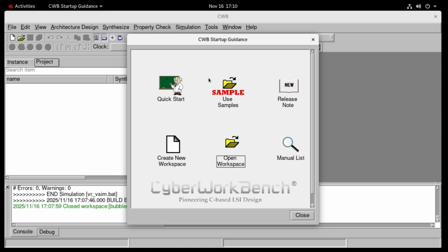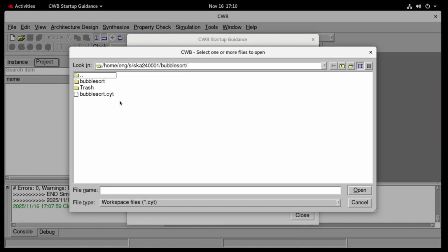Implement high-level synthesis optimization, and we will learn how to control the synthesis result of the HLS generated circuit through different synthesis options like arrays, loops, and functions. So we will go and implement the bubble sort algorithm. So I'll go and create the new project.